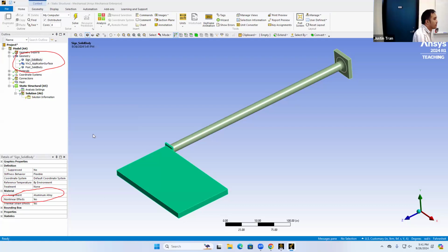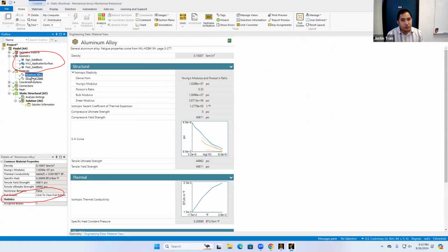Yes, question. Is there a difference in what ANSYS does if you switch the material in that menu versus making a material assignment in materials? Wait, a material assignment where again? On your materials, like if I right click the materials folder, right? It should be the same, so if you do either one, it should give you the same. Yeah, typically I do it under geometry just because I know this one opens up the menu, so it's a little bit hard to visualize the part. But it should be fine to do.